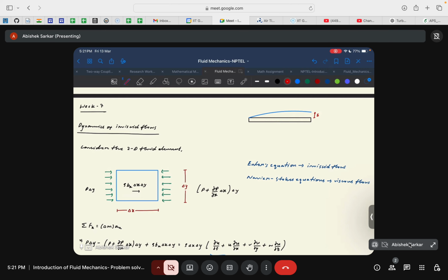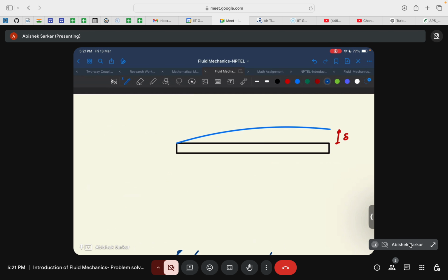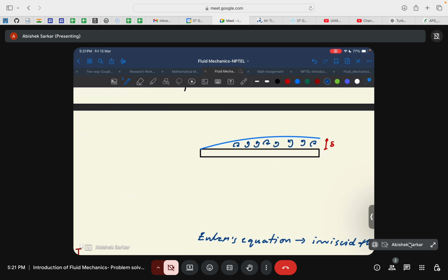What it means is that all the viscous effects, such as the vortical structures that carry the information of the presence of the plate from the plate to the outer flow, are confined within this small region. So this region will be highly rotational and have highly viscous effects. Now you may ask, what happens beyond this region?